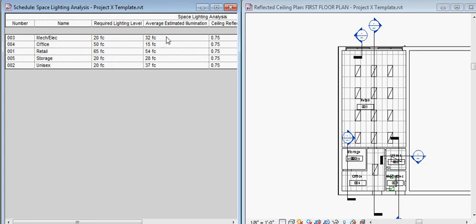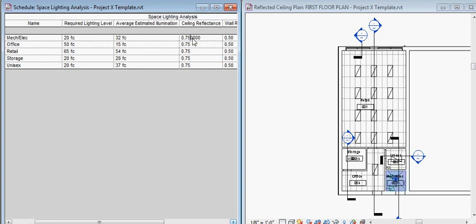Now I could do a few things. I could bump down to just one lamp versus two. I can try to raise the light fixture, see if that would correct it. Or I could change the wall surface material or reflectance, whatever the paint is, or if it's CMU or whatnot. I can specify what that value is, which can control that foot-candle level. So I can try to get down to what I need without maybe even swapping out the fixture or going with a different bulb. So that's available now for you.